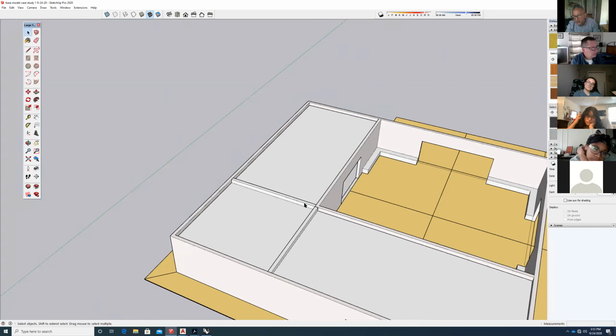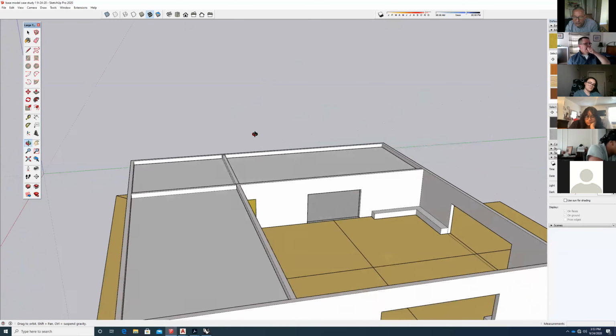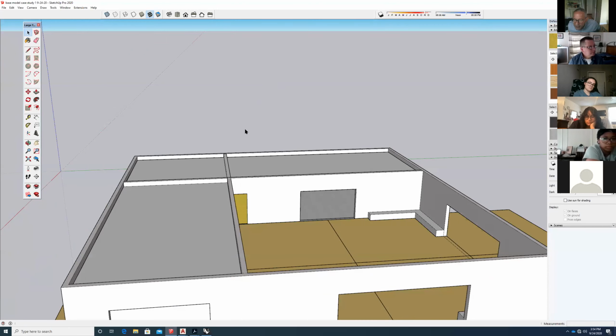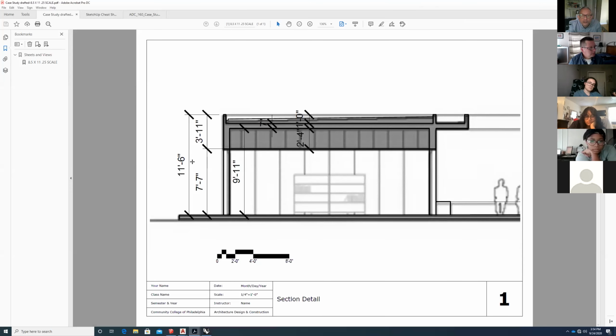So I did these guys kind of quickly, but if you look at the roof plan and some of the axonometrics, these parapet walls extend. And for the sake of simplicity, because we really won't see them that closely, if you look at your plans, the parapet walls are actually narrower than the walls below. So you see, this is the wall coming up. It's only about 4 inches thick, but just for simplicity's sake, we're going to make it the same depth as the walls below.